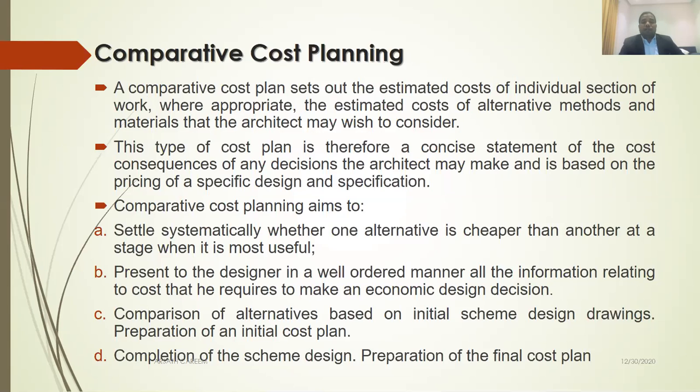Also for the slab, for the structural part, you can design with flat slab or slab and beam. Some other techniques are available. So the designer will design both, whatever the available methods, and he will give it to the quantity surveyor. So you have to price both of them, then compare the price, and the team will decide which system to be implemented.